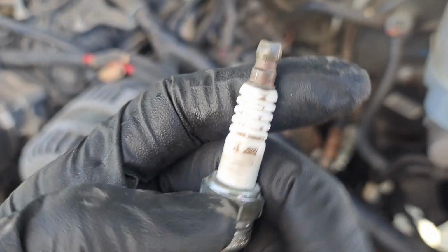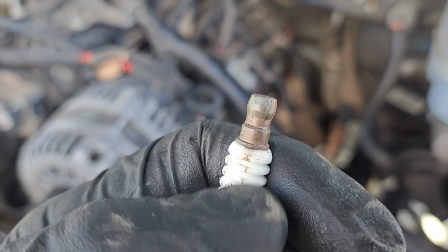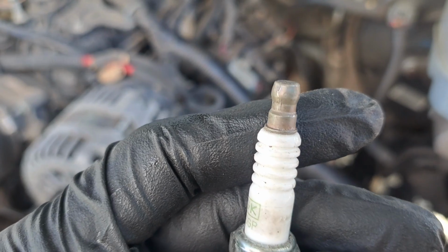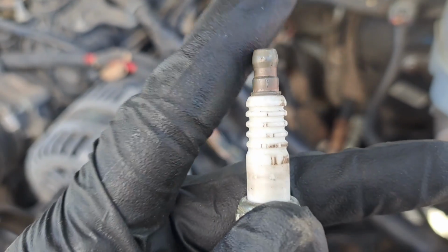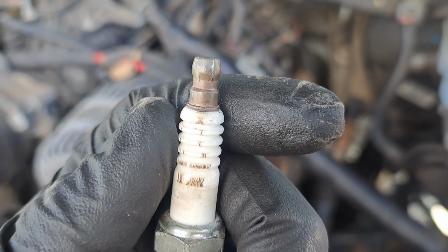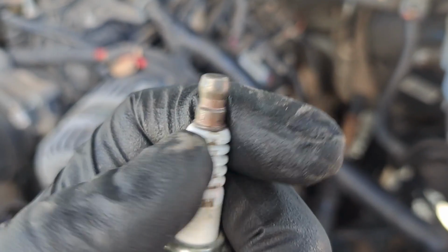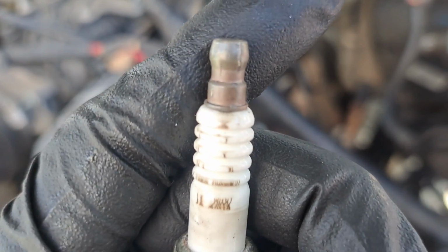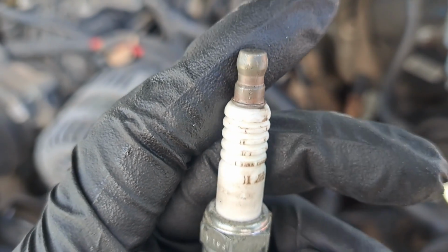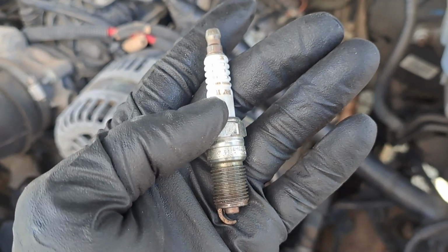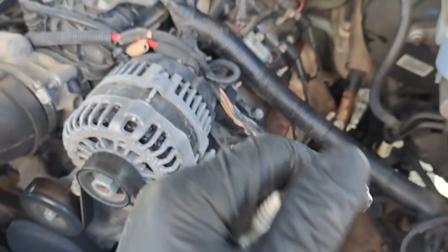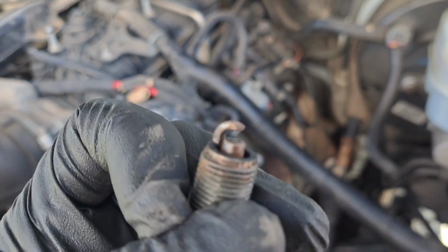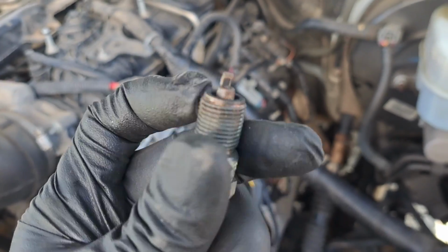Look at the sides here, the porcelain. This is not rubbing off. We just had some misfires on this bank too. It wasn't showing on misfire scan data, because I went to look at live misfire data and it didn't show. But this not rubbing off is a good indication that we likely had some arcing from this plug under the right circumstances. Some vehicles are a little bit more sensitive when it comes to misfire than others, but we definitely are dealing with inefficient burn because of that excessive gap.